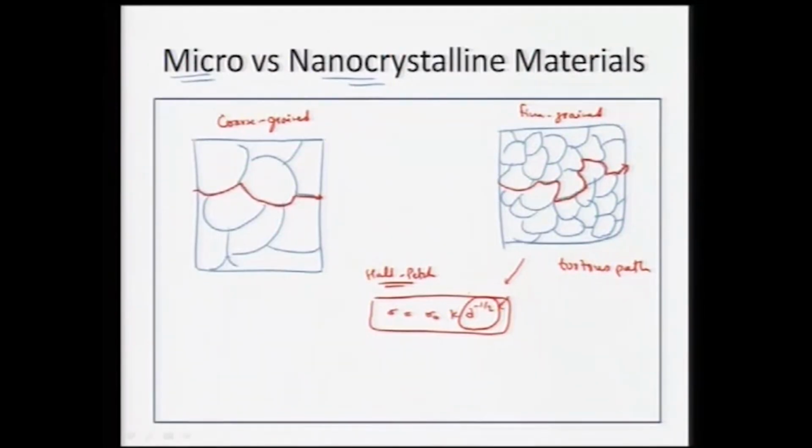So, that part is true for the nanocrystalline material, that we can enhance the strength of the material via reducing the grain size, but that is true only until around 20 nanometer of grain size, and below that the inverse Hall-Petch relationship also comes into the picture. That means that for grain size lesser than say around 10 or 15 nanometer, the strength also starts degrading.